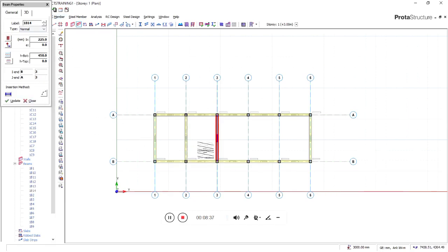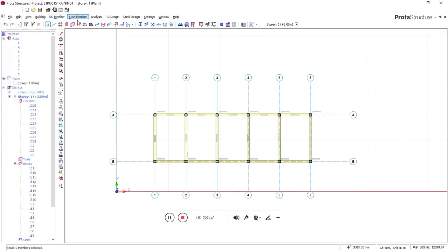You understand? It's still there. You don't have to go back and press escape and then go and pick beam again at every point. No, you right click to escape this one that you have drawn last, so that it will allow you to go to the next place to do whatever it is you want to do. You right click again, and that's all. So you can press escape now, and you close this beam properties, and then you want to do slab.